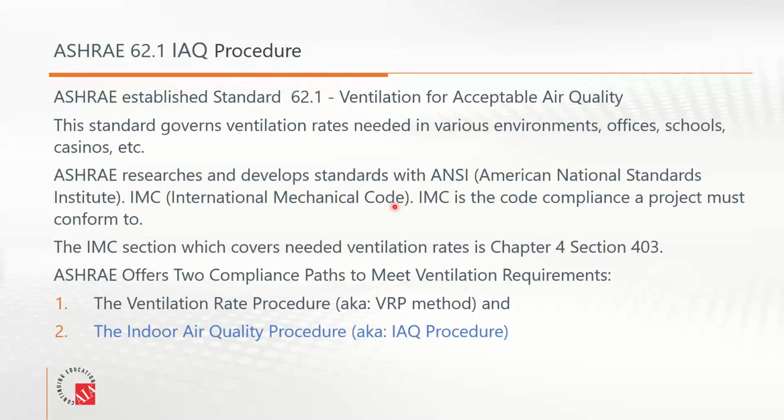One of the things that was mentioned in the video was the ASHRAE 62 indoor air quality procedure. And this is where it comes into play with the energy. If you're able to improve your indoor air quality with an electronic air cleaning technology, you have the ability then to use the IAQ procedure, which actually will allow you to reduce your outside air ventilation.